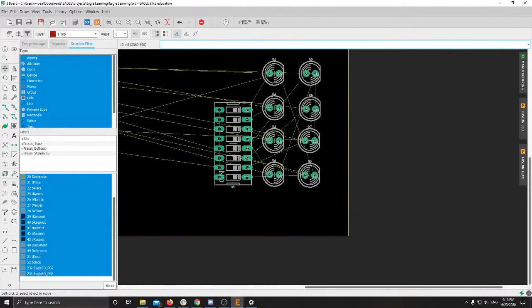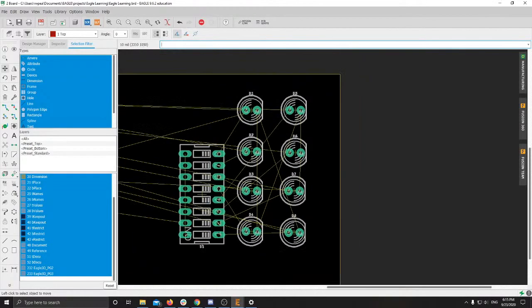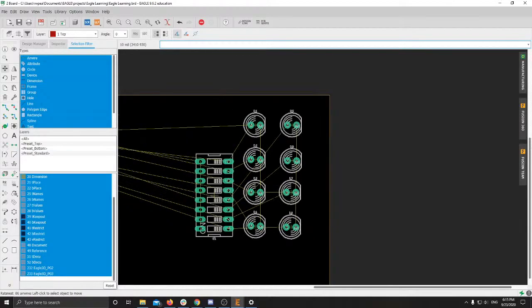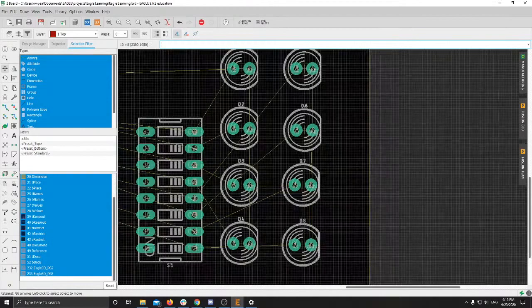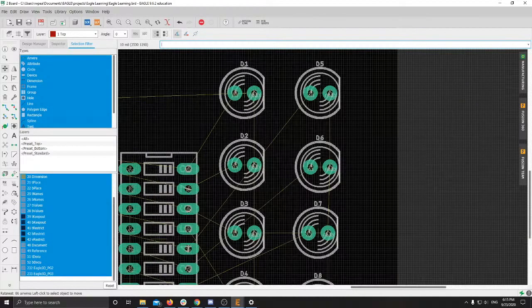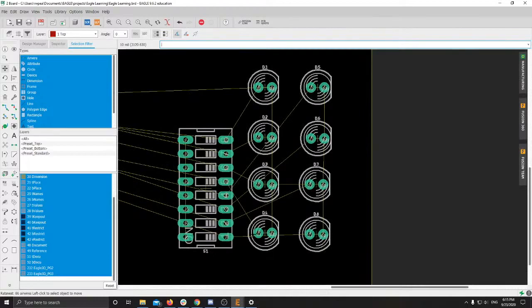So now, once we have this, this is where the rat's nest tool comes in. So you see, okay, this is just spaghetti here. Everything's crisscrossing. You're not actually going to route like that. It's not helpful. So what we're going to do is you come over here and you see this little 5-pointed shape, I guess, or connected dots. And I'm going to click it and you'll see, oh, wow, that's a lot neater now. So it just found the optimal way to connect these. So instead of having these grounds going all over, they can connect directly like that.